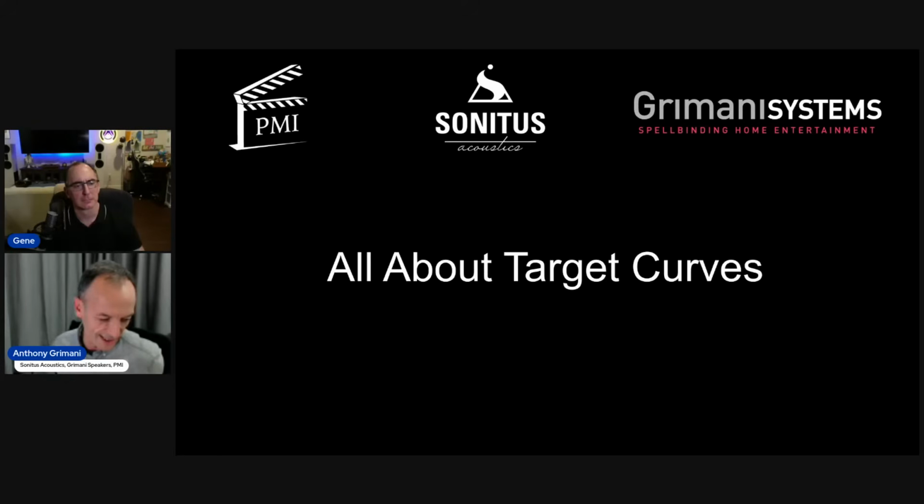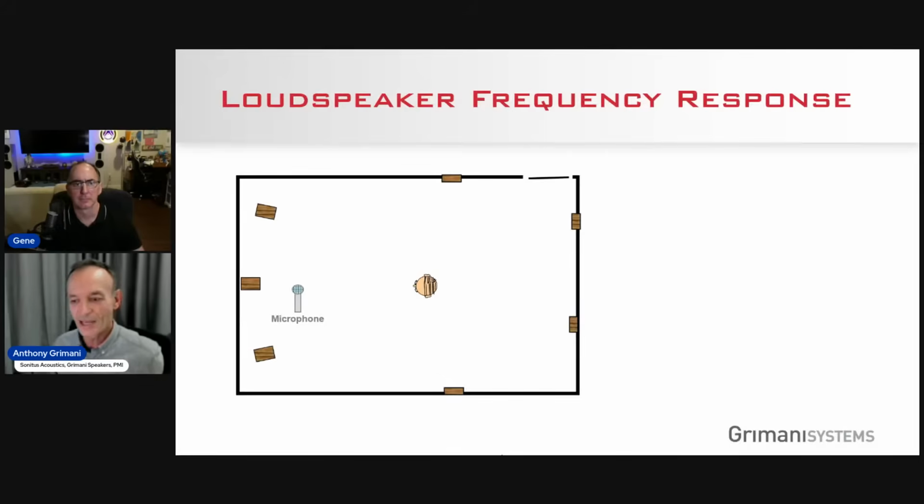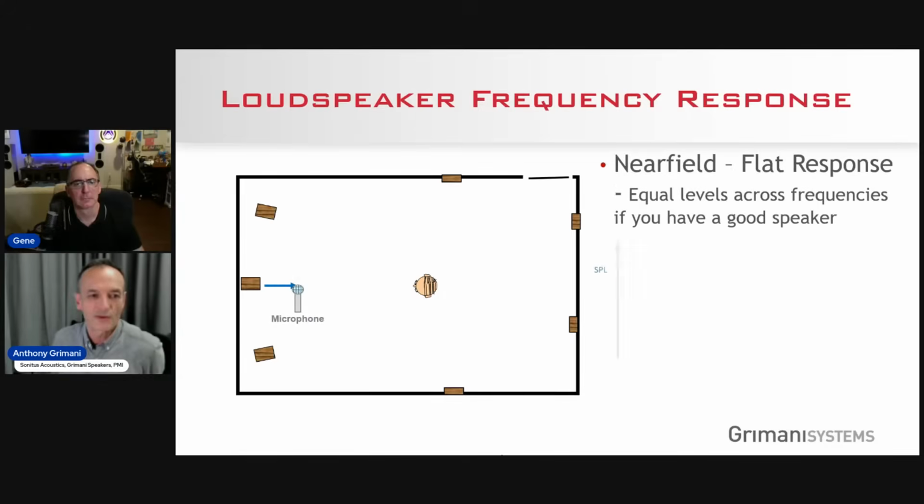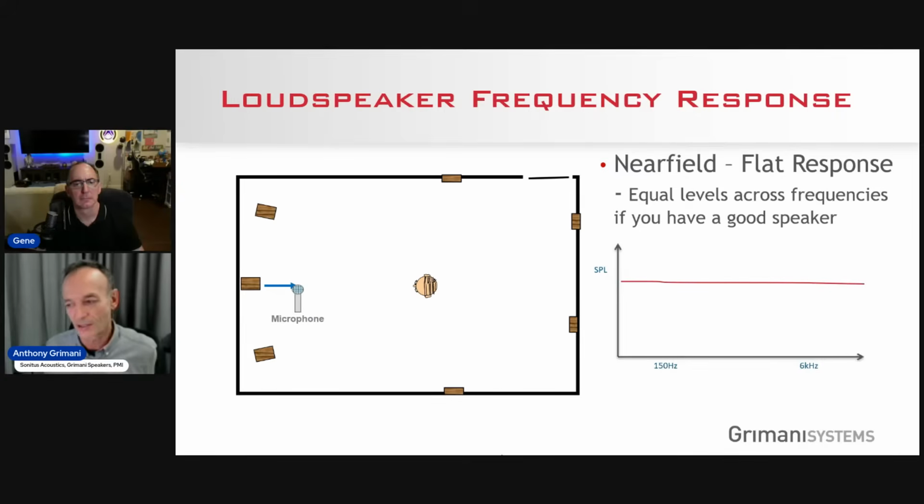And I broached the topic of, hey, when you take a decent speaker and you measure it 2 to 3 feet away from the speaker in what's called the near field, which is where your measurement or your listening, if you're really close, is dominated by the direct sound from the speaker to you. There's always reflections in the room, but if you get close enough to the speaker, you're in the near field.